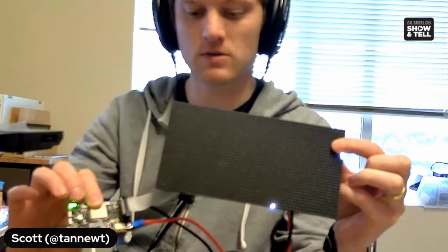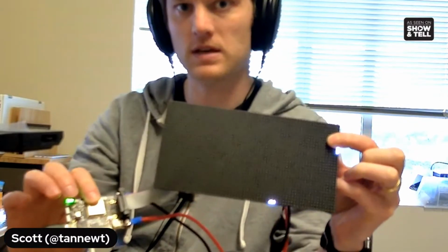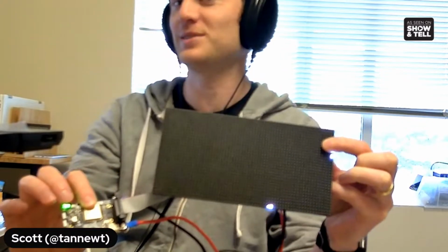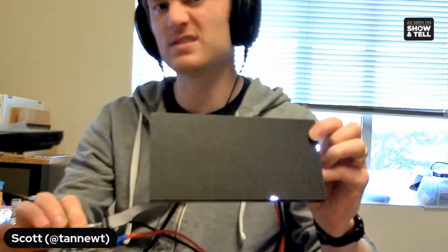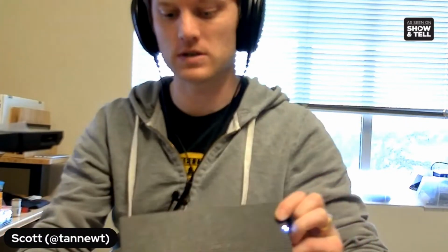And I just fixed a bug where when you access USB and the flash disappears, it shouldn't crash anymore, hopefully, knock on wood. Instead, it'll just pause the update while the flash write is going. The reason is that when you're writing flash, the PSRAM becomes inaccessible. So if you have your big frame buffer for Matrix Portal or ProtoMatter in the PSRAM, you can't actually access it. So I'd update it if I could, but you probably can't. So I've been working on that.